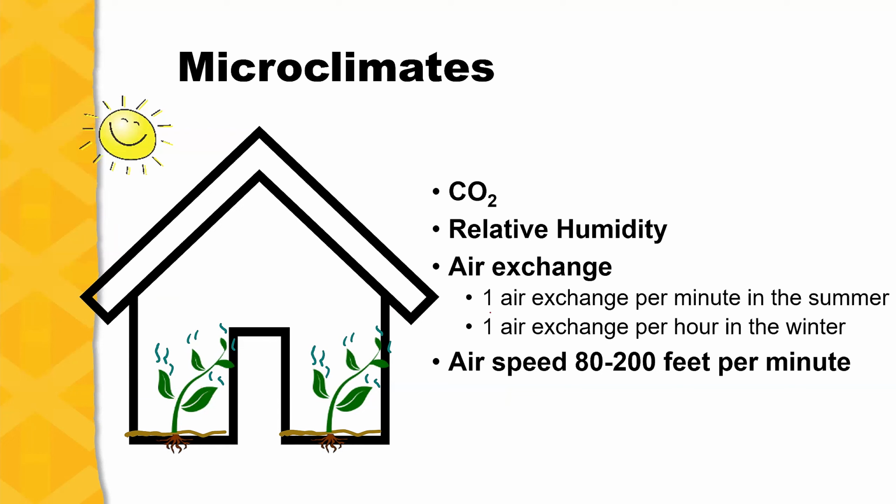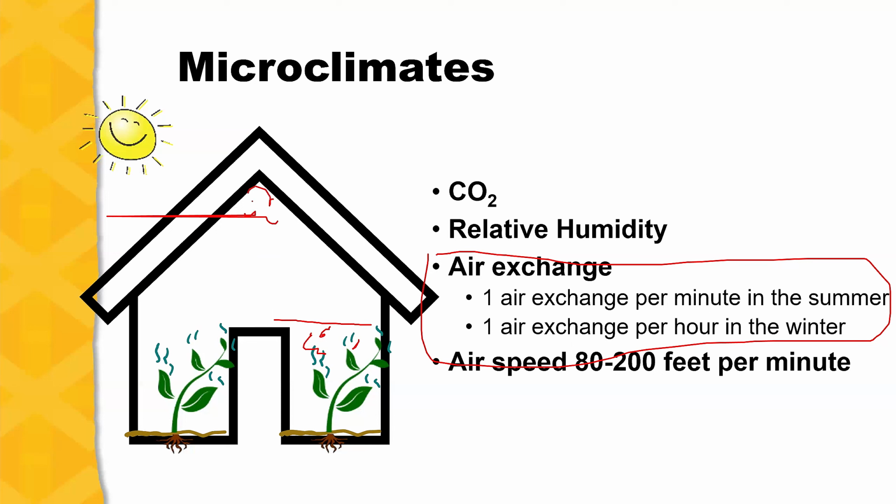So that's why you want to have air exchange in the greenhouse. That's why you want to move air, because you want to prevent low CO2, but also you want to prevent high buildup of high humidity. And we talked about that horizontal airflow fans also helps mitigate this, because usually the high humidity air is going to stratify with higher humidity closer to these locations and lower humidity air up here. So that horizontal airflow fans is going to help you homogenize this air, right?